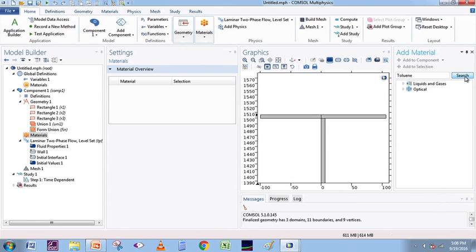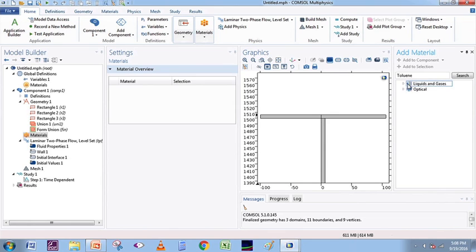And in iterative solvers we have GMRES, the best. GMRES stands for generalized minimal residual approach. In GMRES it is actually like the Gauss-Seidel iteration technique, which assumes a solution, then goes on iterating until it meets the required convergence criteria. So, as we see there, it has arrived.